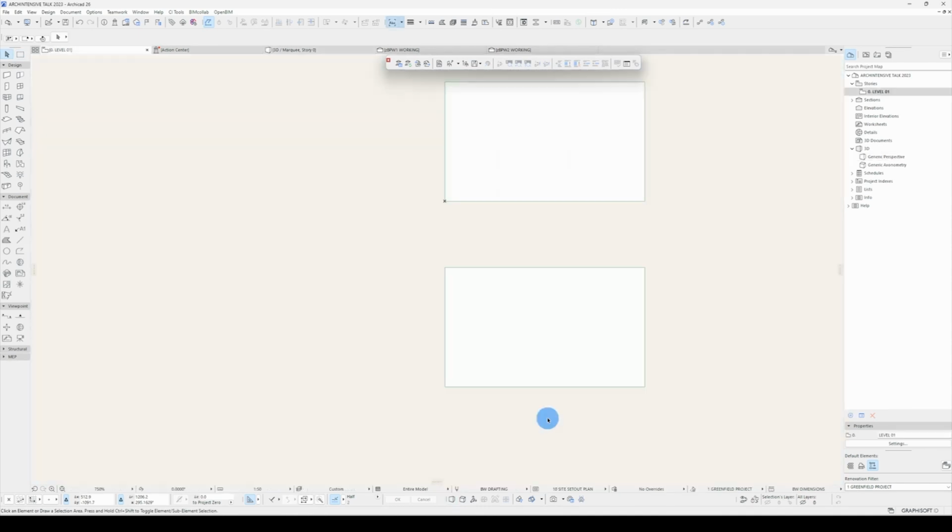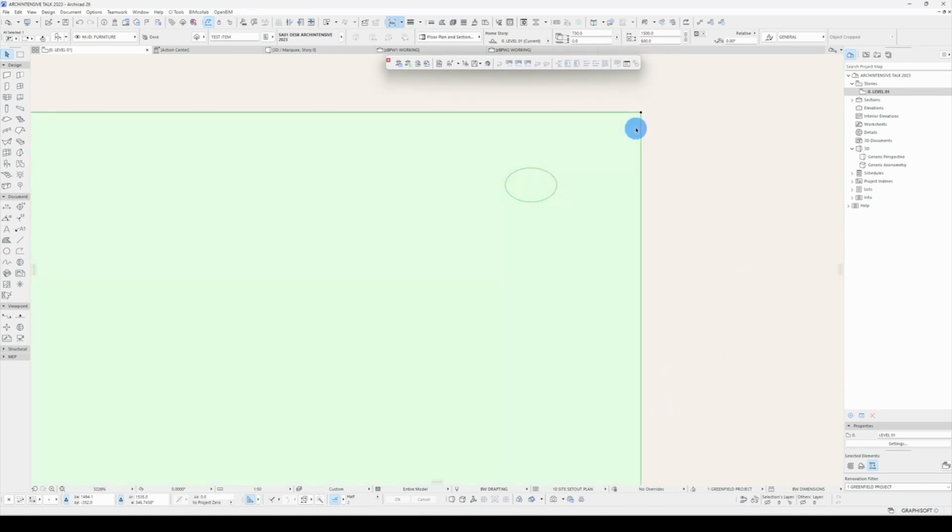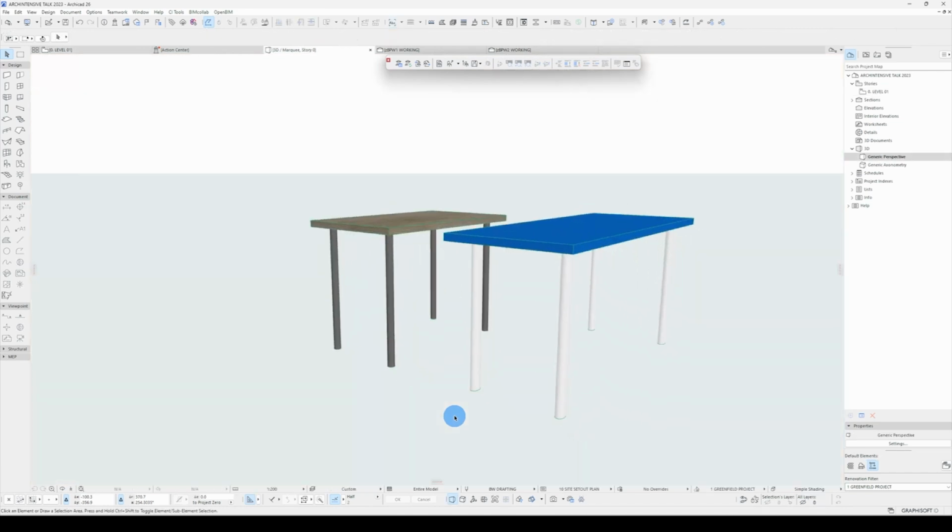And that's it. The downside of this technique, there are two downsides. One is that this size is not fixed. So if I were to change this size up to say 1500, you can see that yes, it's applied the size change, but it's just applied a scaling to the entire object. So these legs have been stretched, which generally is not what you want.